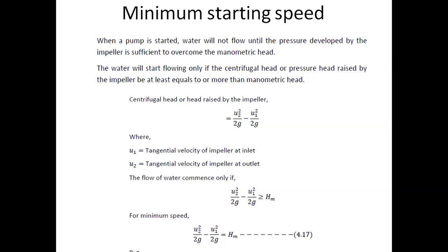The water will start flowing only if the centrifugal head or pressure head rise by the impeller is at least equal to or more than the manometric head.